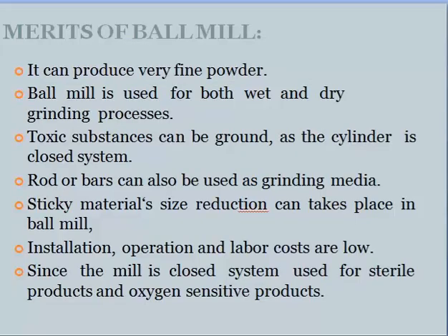Now, merits of ball mill. It can produce very fine particles. Ball mill is used for both wet and dry grinding process. Toxic substances can be ground as the cylinder is a closed system. Rods or bars can also be used as grinding media. Sticky materials size reduction can take place in ball mill. Installation, operation and labor costs are low. Since the mill is a closed system, it is used for sterile products and oxygen sensitive products.